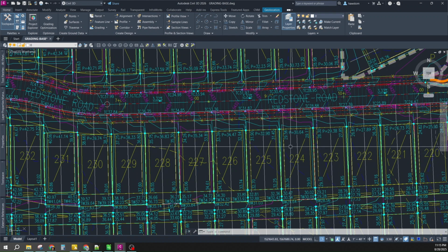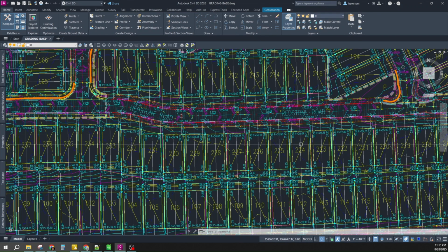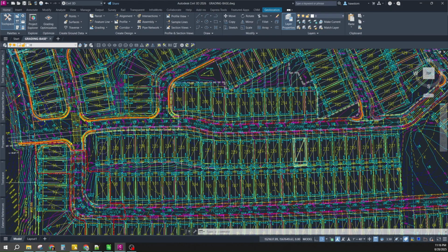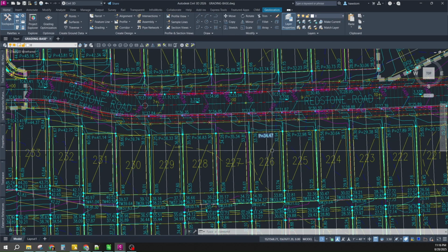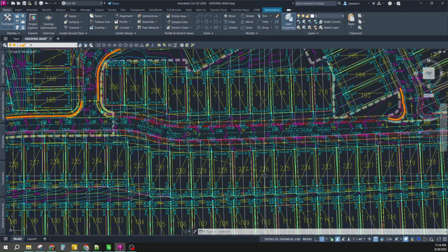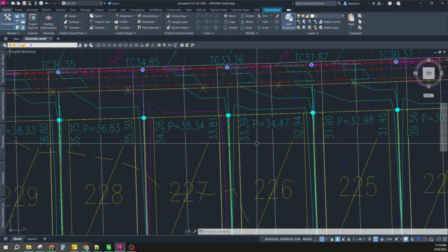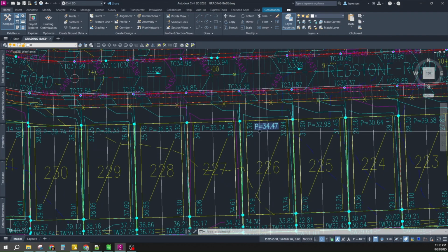The question is, how do we put those on all the lots? And that we do with the MoCoRo, move, copy, rotate command that I wrote that lets you choose a selection set. So we would choose this feature line, choose the base point and rotation, and then choose a target selection set of objects or blocks, and it will copy, move, and rotate that to every single one. And by having a pad block on every lot, we were able to copy these to the lot.